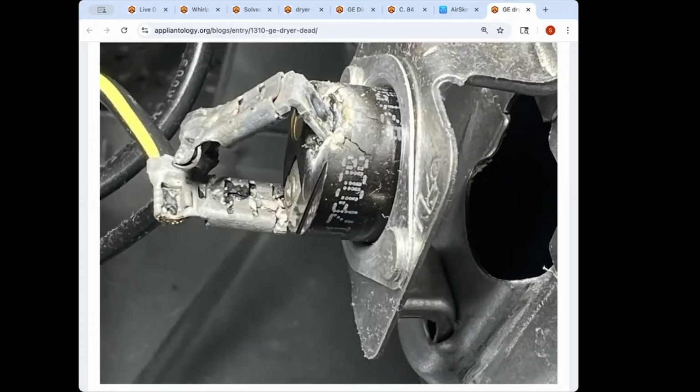Sometimes it can be an internal thing. It's not even one of your external terminals that are loose. It could be something that's failed internally where now suddenly, a closed switch, we always say a closed switch should be like a piece of wire. Technically it's like a tenth of an ohm or something like that. We don't worry about that for troubleshooting. We call it a piece of wire. Well, you start getting 1 ohm, 2, 3, 4 ohms. It doesn't take much, especially at 23 amps. You're dropping significant voltage across that, and you're producing feelable heat. Enough heat to do damage like this.